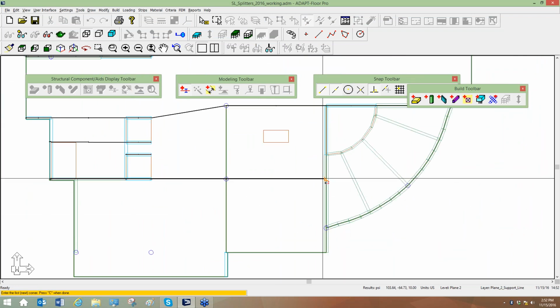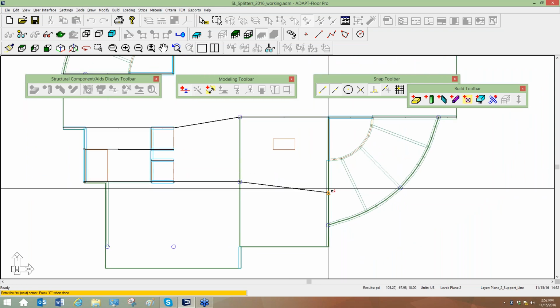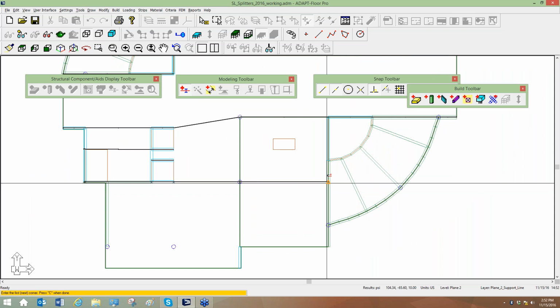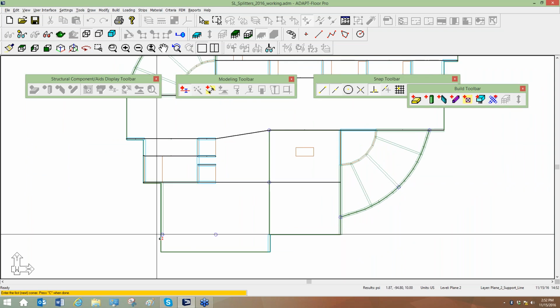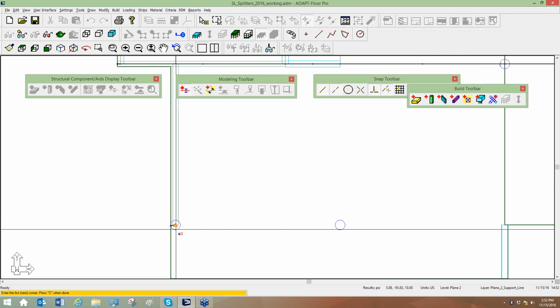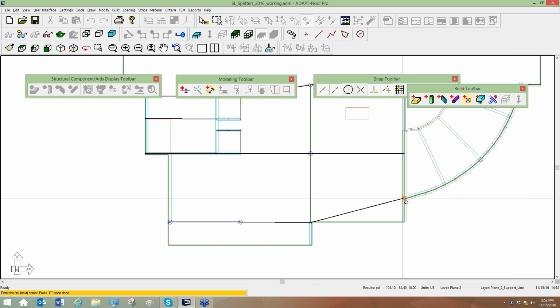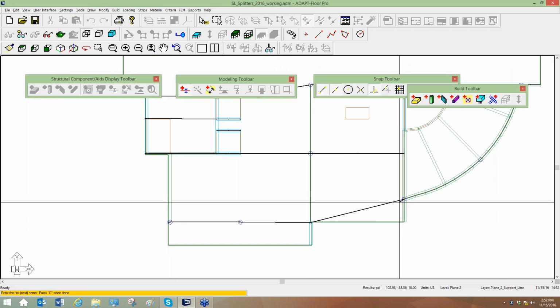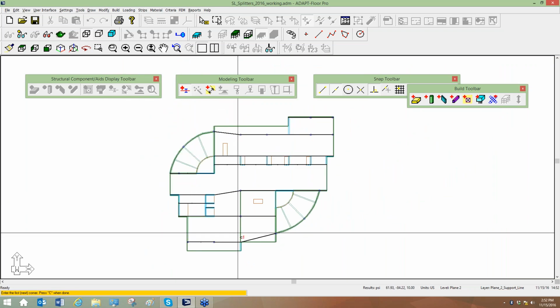Okay, now this beam I'm going to assume is a support. In reality, I probably wouldn't. I would not anchor the banded tendons at the midspan of a beam, but for sake of just keeping this aligned, I'll dead end that support there, and then we'll go down to this next line, and here we'll go up to this support right there. So here I have not added any splitters at all. I just added my support lines.